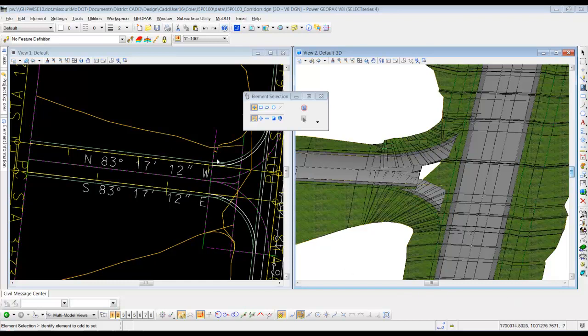Alright, once we have the corridors for ramp 2 and ramp 4 placed in our corridors DGN, we're going to have to create a match line that's on the north side of ramp 2 and at this location where ramp 2 and ramp 4 meet on the edges of pavement, and runs all the way through the Bighorn intersection so that we can target these corridors and make it fill out the remaining missing area right here. And we're also going to use point controls and target the edge of Bighorn. To get started with this, we need a match line that runs down through that we can target.